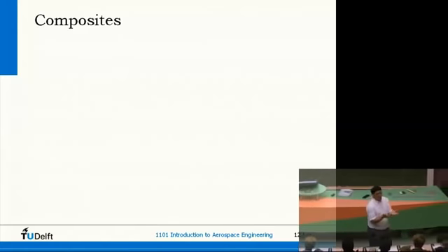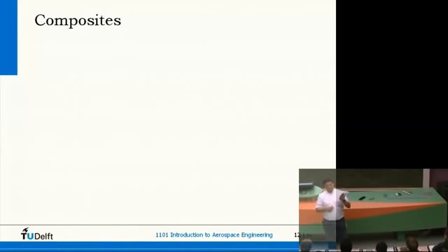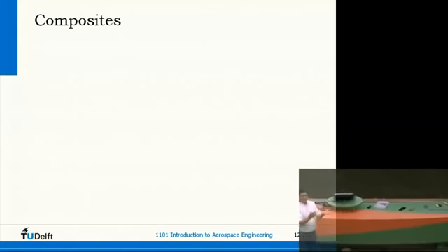If you have thermoplastic materials, you bring the two together and you have a local heat source like a laser. You can locally melt them, push them together, force them together, and you get a weld. It has not really become fluid, not a very water-like material in between. It is some paste material. Whereas in metals, you really make it fluid, you really make it liquid. But indeed, it is some kind of welding. Local heat source and pushing together, and you have a weld.